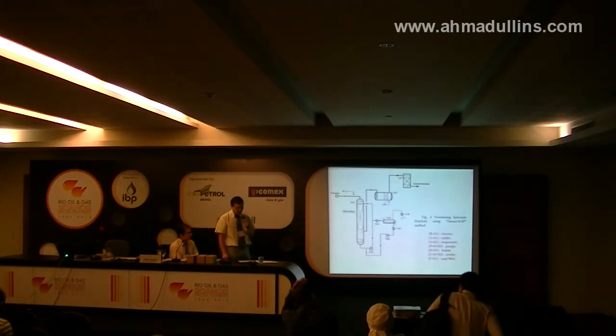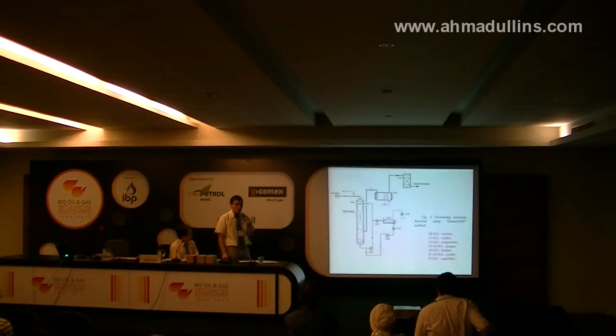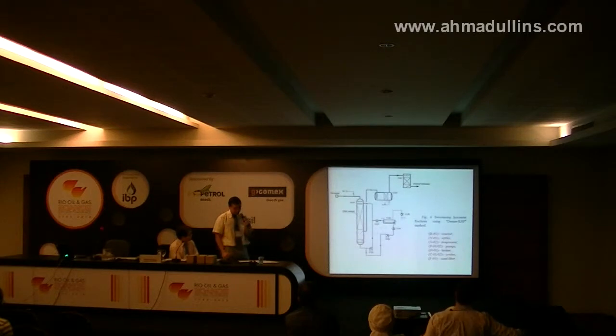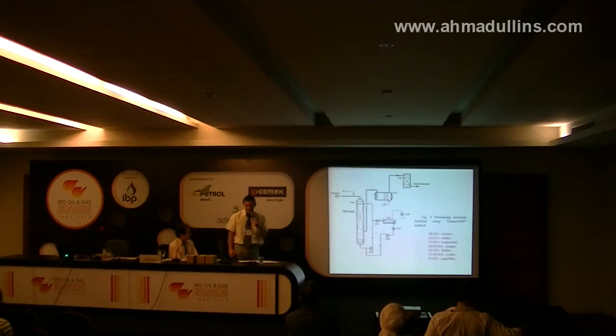Instead of this process, see figure 4, we propose a two-stage regenerative low-waste demercaptanization method using a polymer-based catalyst in conjunction with a promoter that can quantitatively sweeten in 60–90 minutes. In this case, together with sweetening in the same reactor, the promoter is extracting acidic impurities as well as a part of the reaction and dissolved water, which are then removed while promoter regeneration.